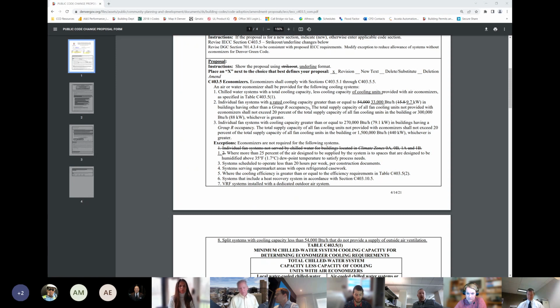Excluding those from an economizer means you're spinning a compressor all year long instead of just opening an outside air damper in our wonderful climate, as like today. Then there's the type of VRF systems that are changeover. They are either a heat pump, but they're either heating or they're cooling. So whenever something needs cooling in that building, you've got to spin a compressor. The whole idea behind economizers is on a day like this, open the outside air dampers and you've got all the cooling you want.